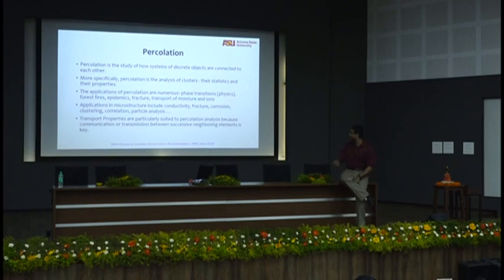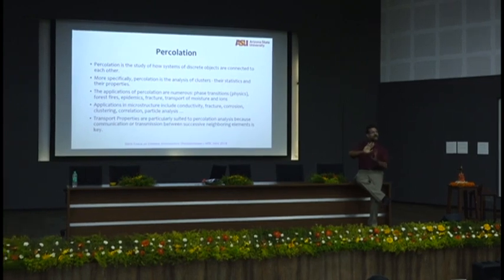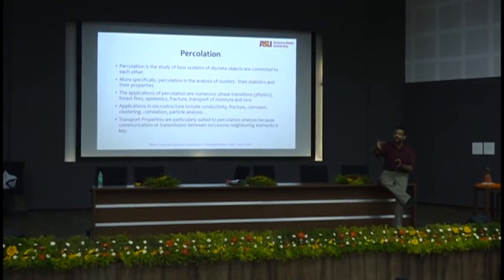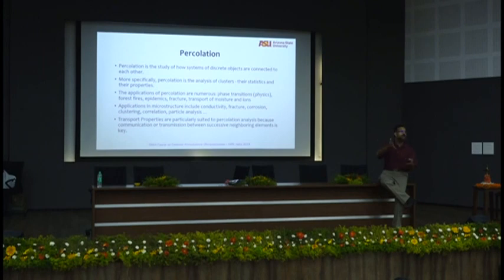But anyway, so fracture, concrete fracture. I'll talk a little bit about fracture and fracture mechanics tomorrow. Fracture also is a percolation process. You have one crack. That crack, unless you do a very quick impact kind of loading, have you ever seen a straight crack in concrete? Crack goes around. Typically the crack tries to avoid the coarse aggregates, right? Because coarse aggregates are strong and dense. Crack goes around. Percolation of cracks. It's trying to find the path of least resistance. Corrosion, clustering, correlation. So we'll do a little bit of all of that.